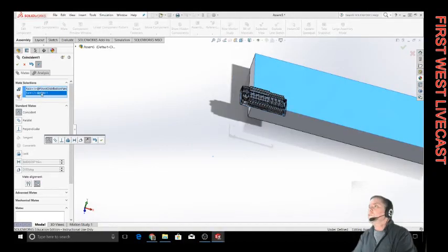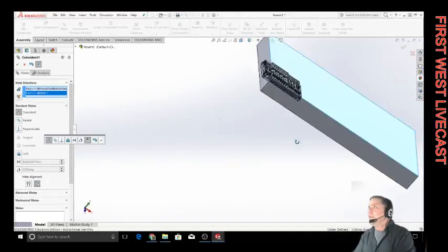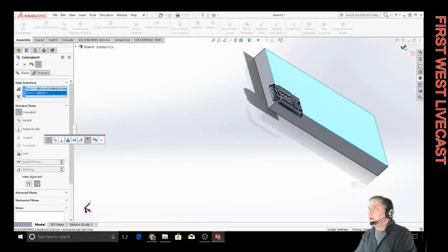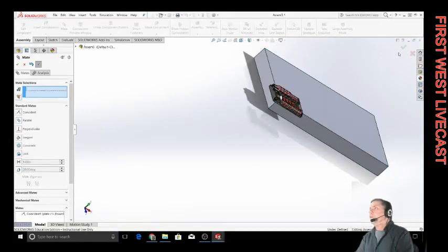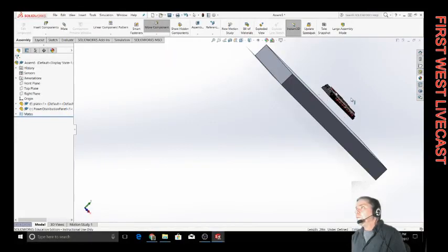Now you see there's two surfaces show up, and the object is now mated on that. You see how it's actually lined up on that surface? I'll click on the arrow here, and that tells me that I'm going to accept this. Here we go. And now you can see this part here can slide around on the surface of this thing.